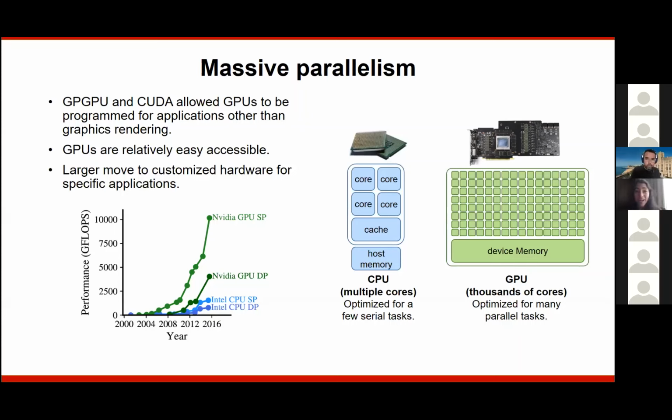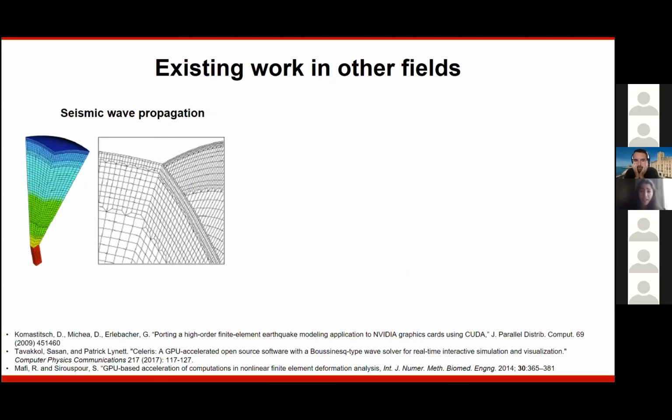And so the entire concept of this is maybe CPUs are parallel in time, where the cores are optimized to do these very specific tasks fairly quickly and high performing in that sense. GPUs are more parallel in space, where you're doing a lot of tasks at once. And so it's really a throughput sort of idea.